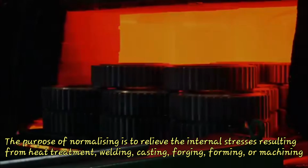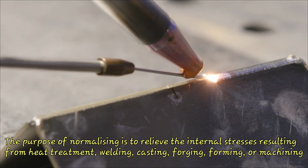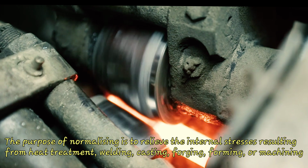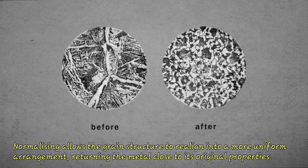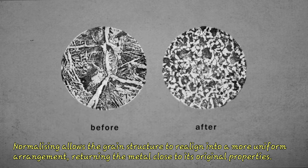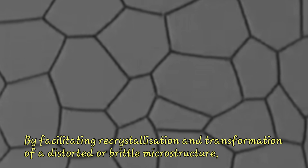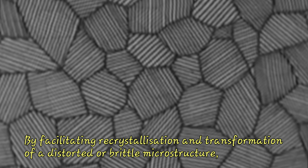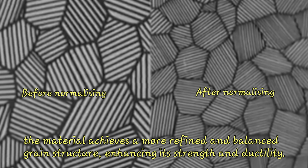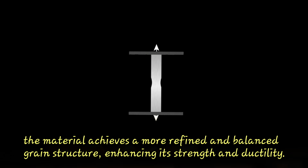The purpose of normalizing is to relieve the internal stresses resulting from heat treatment, welding, casting, forging, forming, or machining. Normalizing allows the grain structure to realign into a more uniform arrangement, returning the metal close to its original properties. By facilitating recrystallization and transformation of the distorted or brittle microstructure, the material achieves a more refined and balanced grain structure, enhancing its strength and ductility.